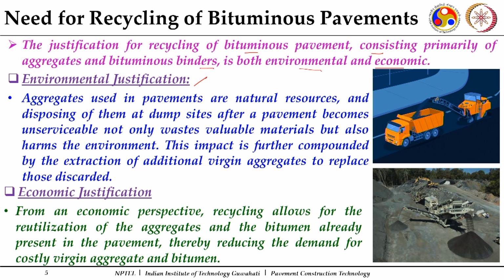What is the environmental justification which we have? The important part is aggregates used in pavements are natural resources, and if one layer has distressed, there is no sense of having that layer, so it needs to be removed. If you are discarding that material at some dump site after a pavement becomes unserviceable, you are disposing natural resources like aggregates. We are not only putting these valuable aggregates as waste, but it also harms the environment, because they have a coating of binder over them.